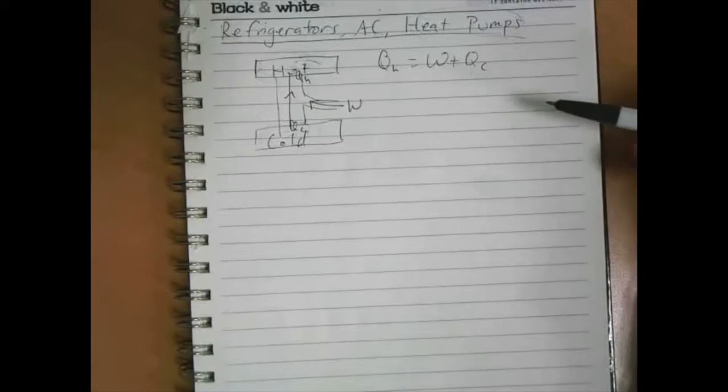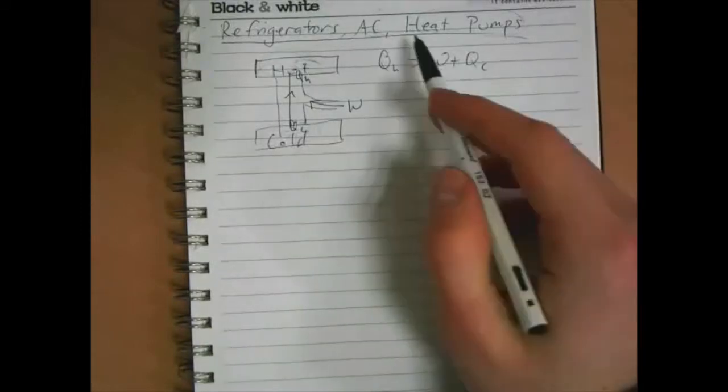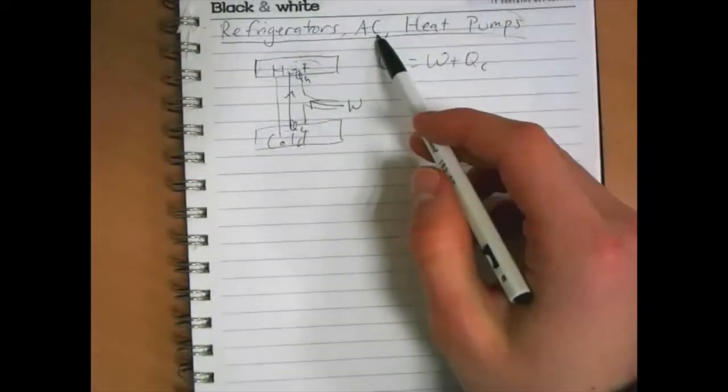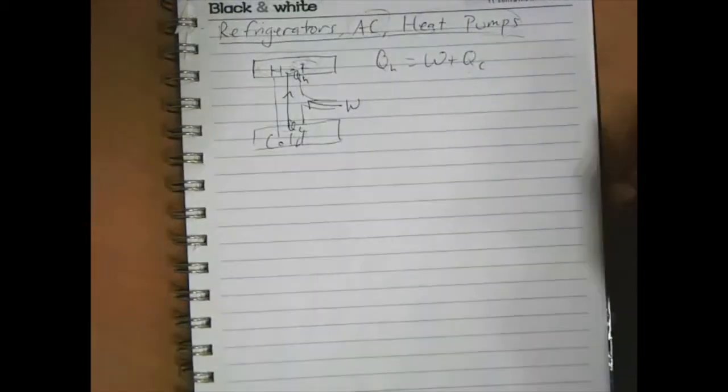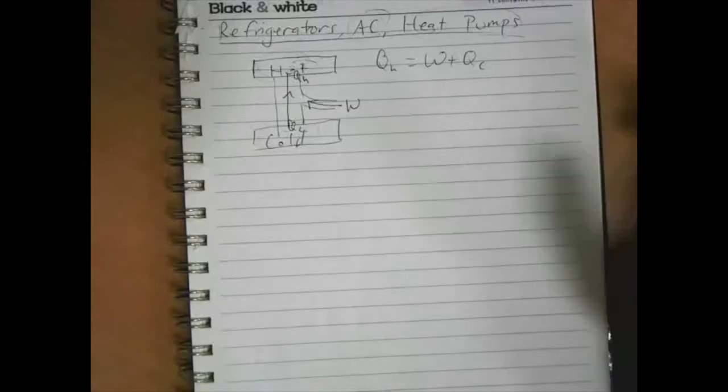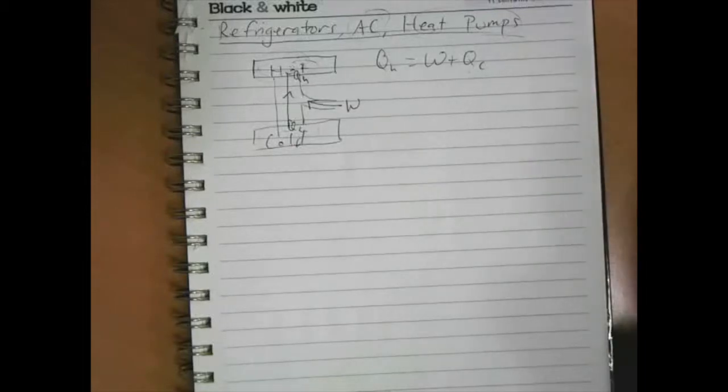An interesting facet of this is that if you take a window air conditioner unit, and you don't put it in the window, you just put it in the room and run it, the temperature in the room is actually going to increase, because there are parts inside the air conditioner that generate friction, so it actually gets hot inside there, and you're turning work into heat.